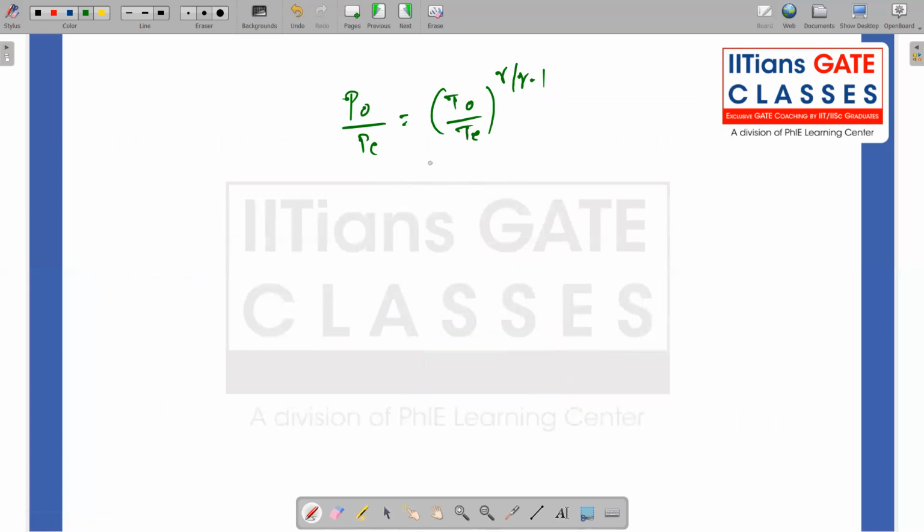Now they are asking me to calculate TE. So I can write TE is equal to T naught times PE divided by P naught to the power of gamma minus 1 by gamma. In the question, the gamma is not given, so we can assume gamma is equal to 1.4 for this particular question. Though that is a missing part in the question, because usually in rocket nozzles, the gases will have a different composition than air.